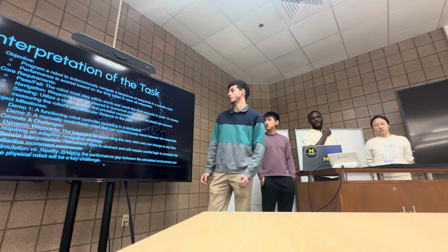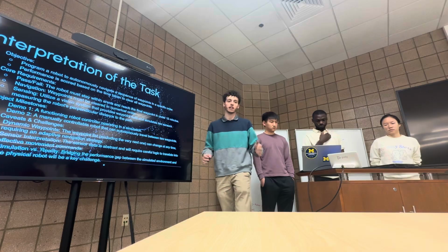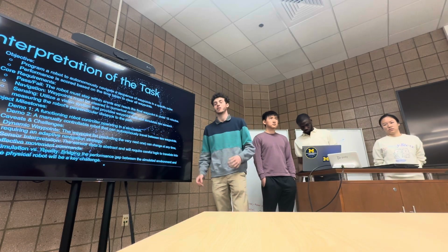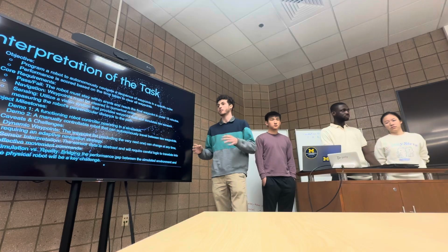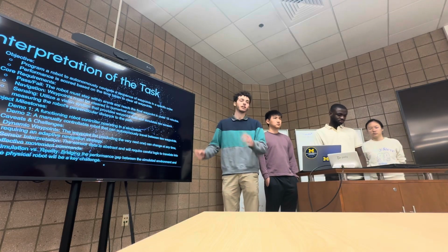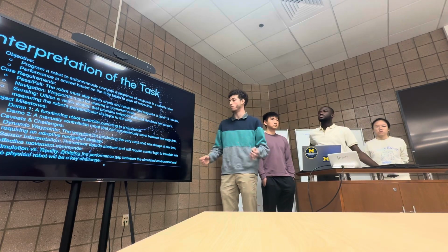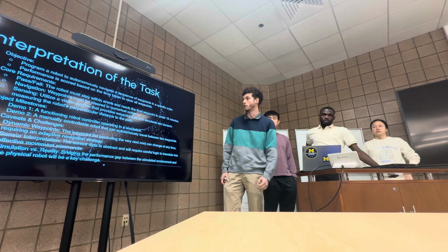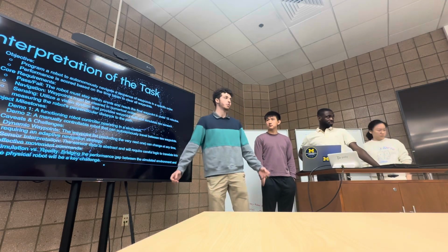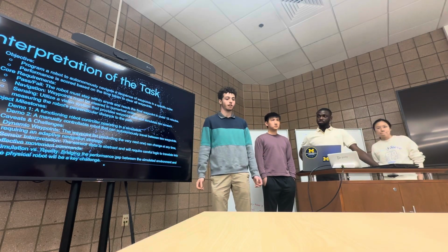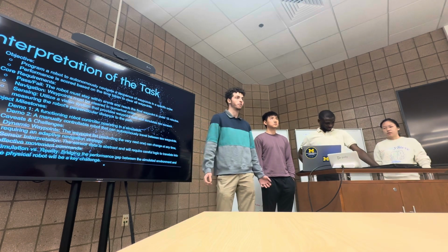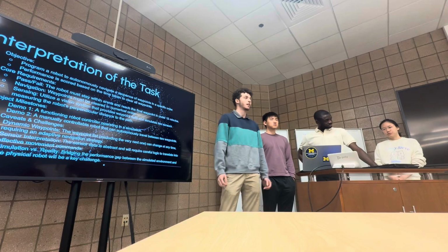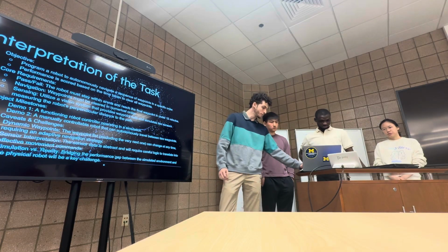We also need to interpret all the sensor information because we're just getting these F and B values, which tell us offset from a line and not exactly our position. We need to convert that into information that is useful for us and can help us navigate to the next waypoint. And then of course there's the difference between simulation and reality. If we can simulate a system that works, that's great, but there's going to be some differences between how a robot moves in a simulation versus how it moves in reality, and we want to account for those too.